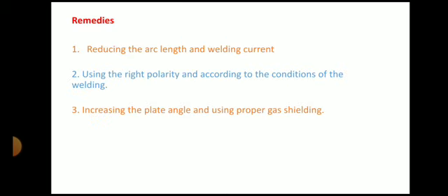Now remedies: reducing the arc length, using the right polarity, and according to the condition of welding, increasing the plate angle and using proper gas shielding.